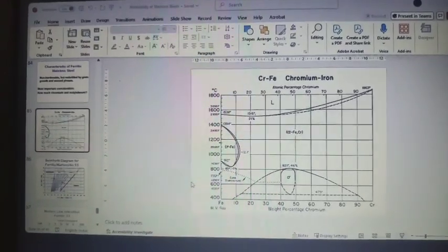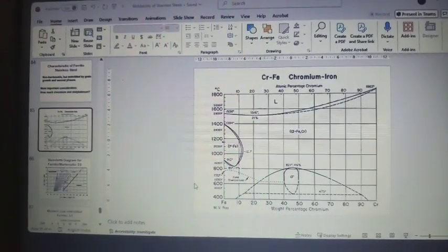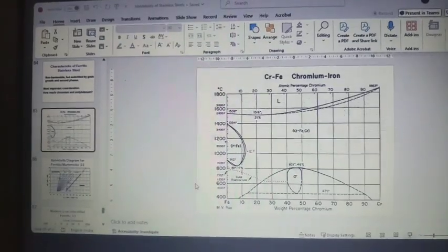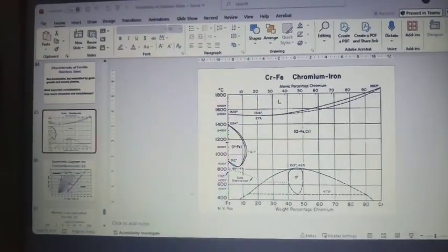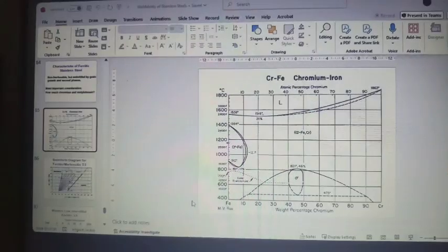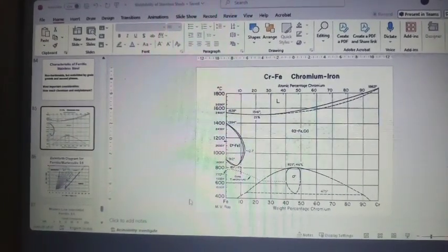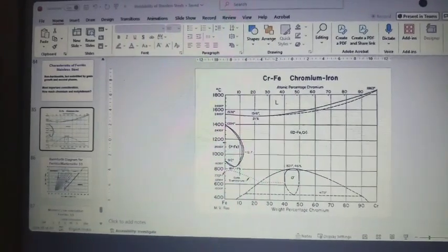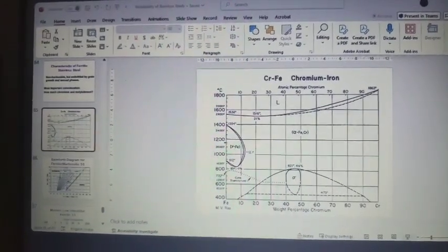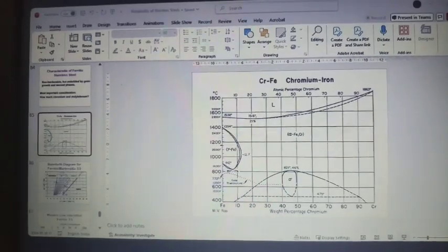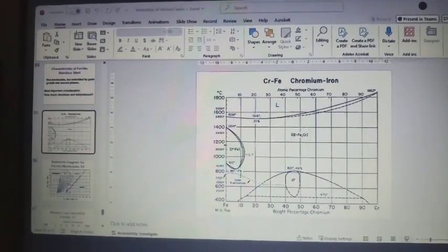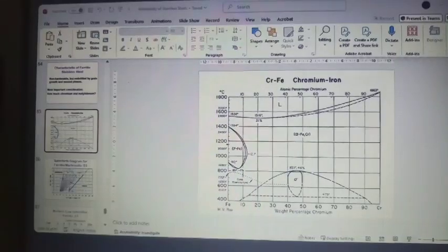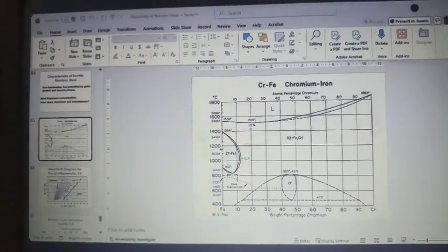We prefer martensitic as advantageous rather than ferritic. It depends upon what you want, because martensitic is used for high temperature application only. Because you have a low chromium, you cannot expect a corrosion resistance like austenitic or duplex stainless steel in a chloride environment. So in chloride environment, generally we don't use martensitic stainless steel.